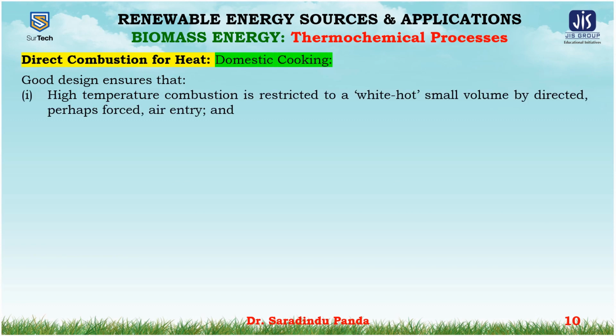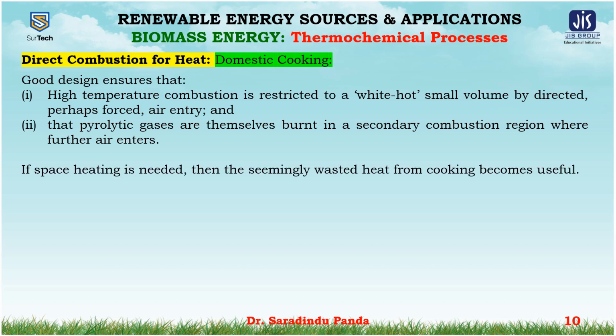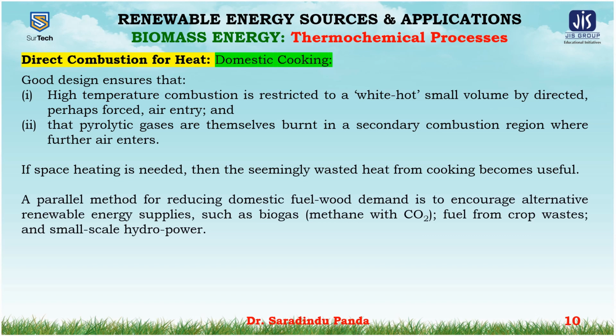Good design ensures that the high temperature combustion is restricted to a white hot small volume by directed, perhaps forced, air entry, and that the pyrolytic gases are themselves burnt in a secondary combustion region where further air enters. If space heating is needed, then the seemingly wasted heat from the cooking becomes useful.